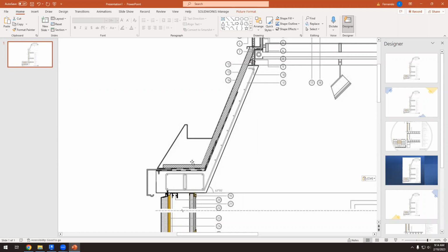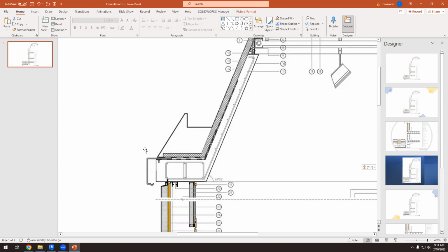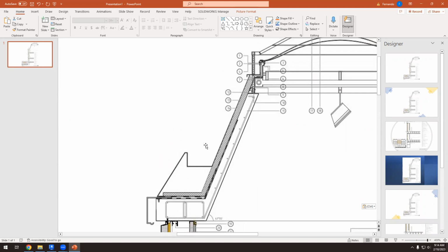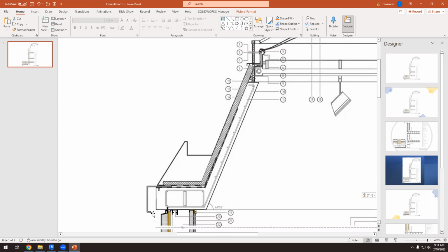And we have explained that in other lessons, not here, but the theory is always the same. So we need to cover this, and this is like a steel plate, because concrete is not good to be exposed to water. So we have to cover this with something made of steel or metal. It can be aluminum, it can be zinc, or it can be galvanized steel. It depends, but we need to cover this with that.